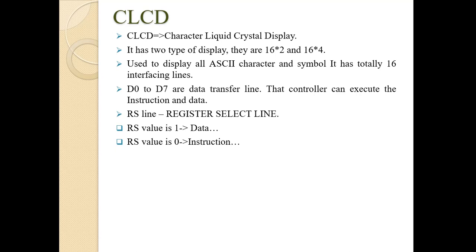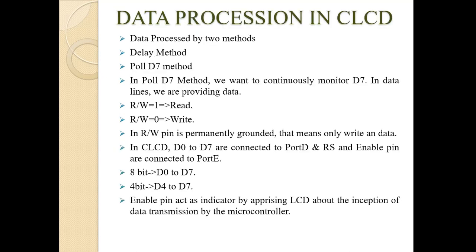The RS line stands for register select line. If the RS value is 1, then the data will be transmitted. If the RS value is 0, then the instruction will be transmitted.